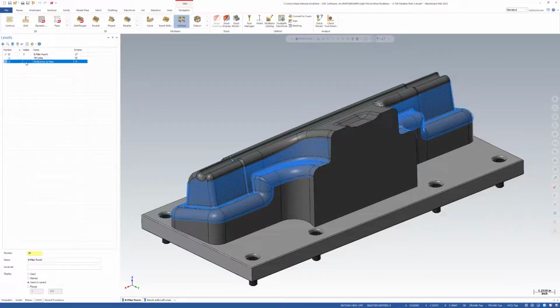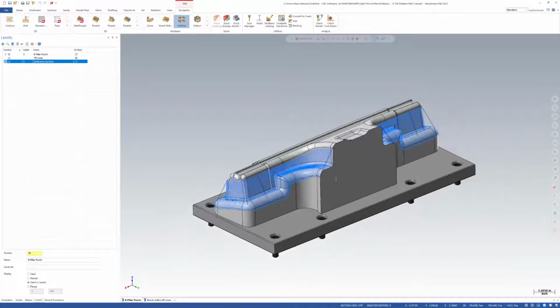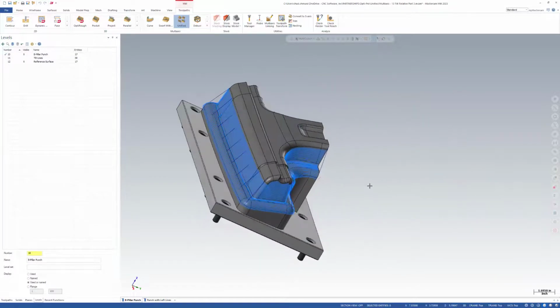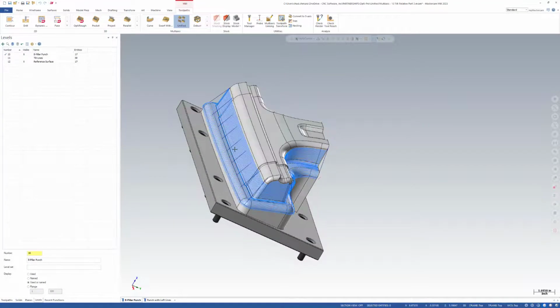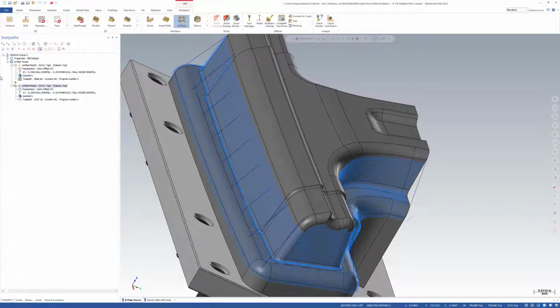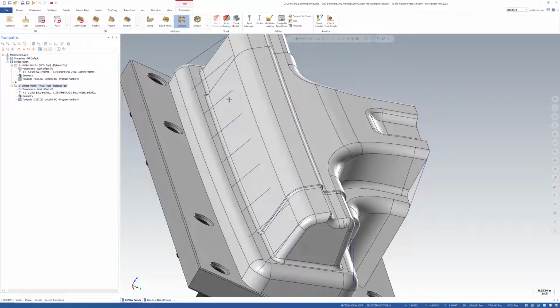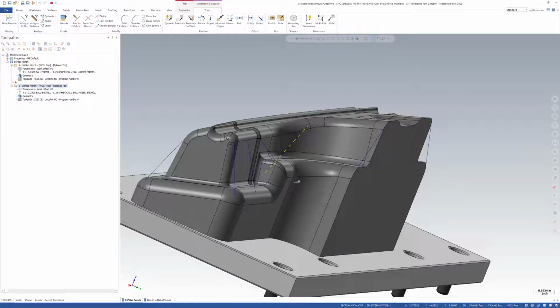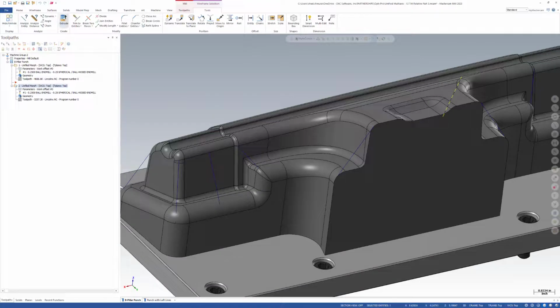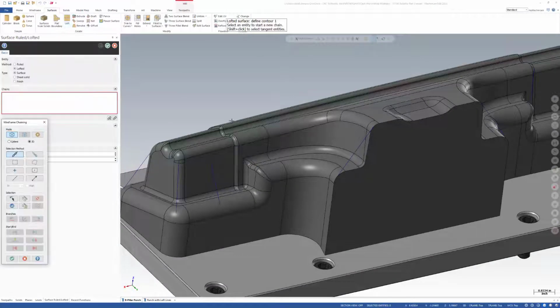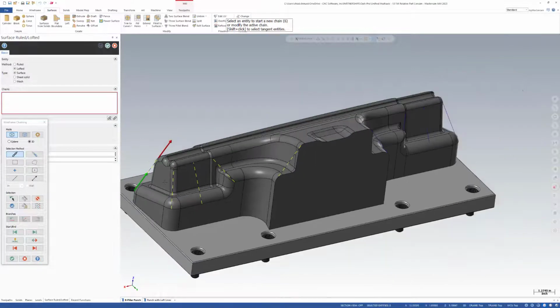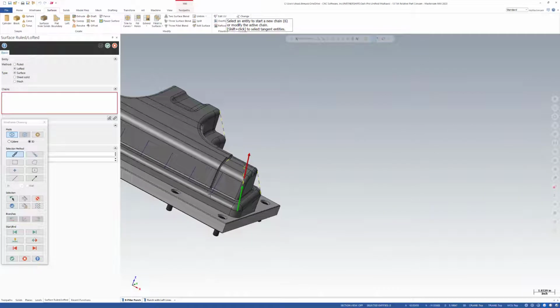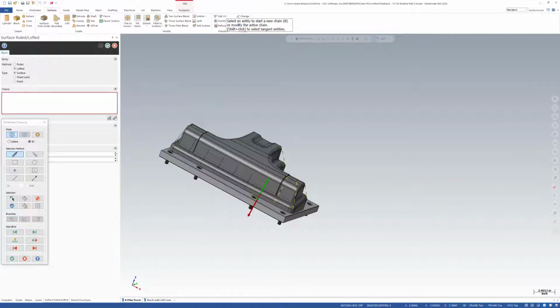Well, in 2023, there's a new tool called Reference Surface. So the first thing you need to do is build that surface. So I've already gone ahead and pre-modeled these lines. You'll see these lines are really just nothing special, right? They're just tossed in there randomly. I basically drew a line from the top of the curve to the bottom of the curve. Pretty simple. So if we create a loft, and we loft all these curves, you'll notice this interface is new in 2023, where if I select one backwards on purpose, for example, and let's go in and select the rest of these.